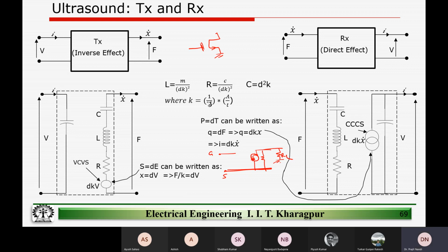And this is nothing but a voltage controlled current source. And the value of the current in this current source is dependent on a coefficient Gm, which we know we can derive, and whatever voltage we are applying here. So let's say V in. So the current source I will be given by Gm times V in, right? And of course, this is the output impedance R0.